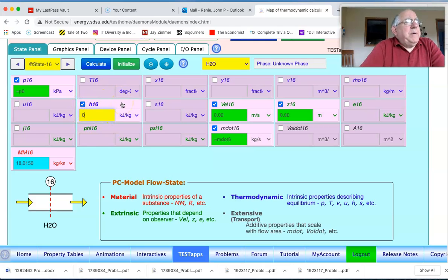Now the enthalpy at 16 is starting at H15. Okay, now that's a crucial piece of information. It's starting as if it was a stage of its own with an actual enthalpy coming in, a real fluid that is at that level because of its irreversibilities.